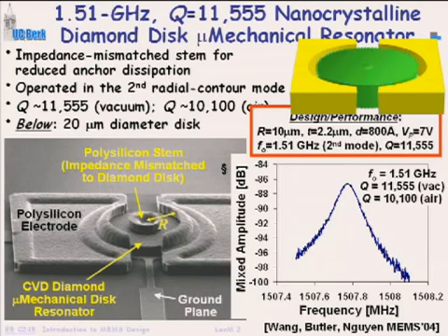What does that mean? That means your signals are going through the capacitors and inductors, which are lossless elements. You have less loss. That's also happening here as well. So the gas damping, which is a resistive damping method, is going away at the higher frequencies as well. So you've got two mechanisms that allow this to reach the Q of 10,000 in air.